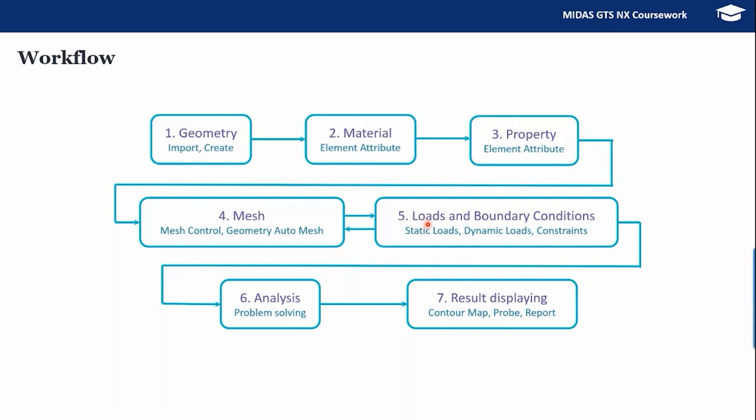In the loads, we are going to apply the ground acceleration, and we are also going to apply the infinite boundaries such as the free field element in this session, as well as the certification task that I'm going to provide you. Then we will analyze the current scenario and see the different results. In the analysis, we'll be solving eigenvalue analysis and nonlinear time history analysis.